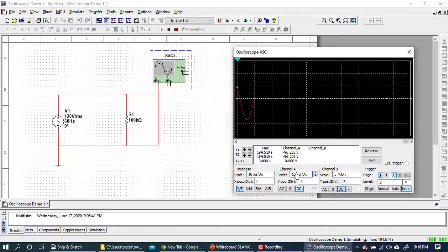Okay, so now that we've got our channel adjusted pretty good, it looks like the waveform is kind of dancing across the screen. And that's okay, but I would love to have a waveform that was stationary, almost looking like it's still in a way. And we can do that. The oscilloscope gives us that capability. The adjustment on an oscilloscope that does that is called the trigger.